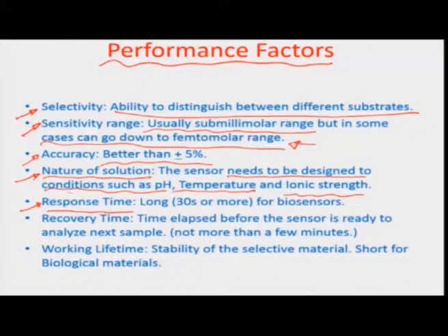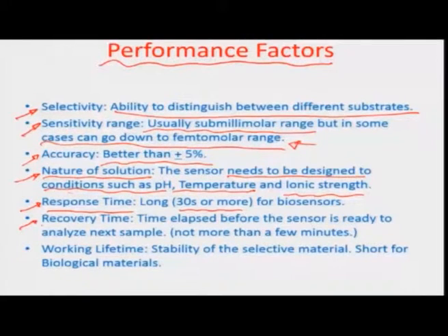Typically for gas sensing applications or biosensors, the smaller the better, but for the biosensing particularly, this level is probably slightly high. With the modern technology, you can say about 30 seconds or more of sensing time is considered to be quite reasonable. There is also a recovery aspect, that once the sensor surface has sensed something, whether it can come back